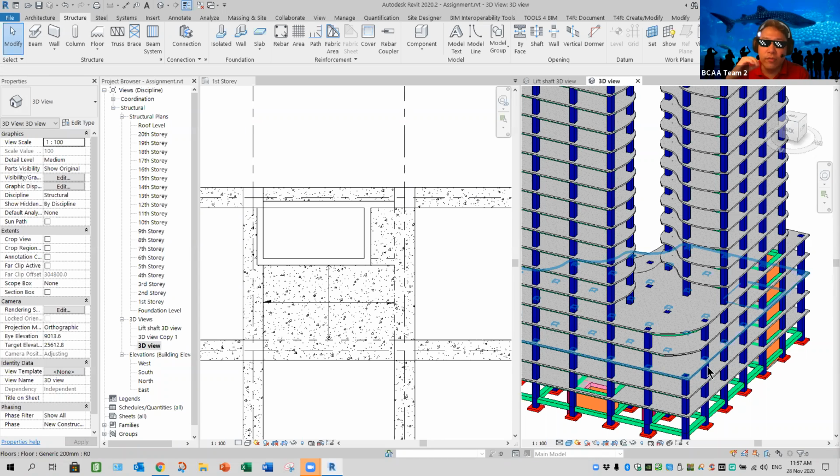If I build the drawing only for the building, then for my structural drawing or structural template, I can use the Archi template as structure. But if it involves calculation, you must use the structural analysis template. So bear that in mind. Two different things.